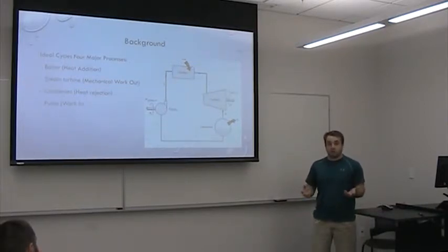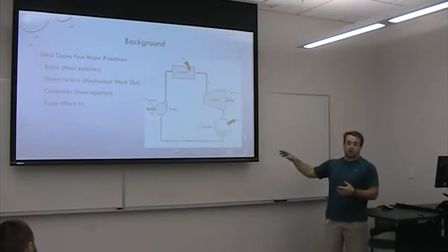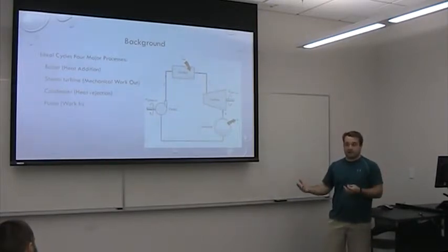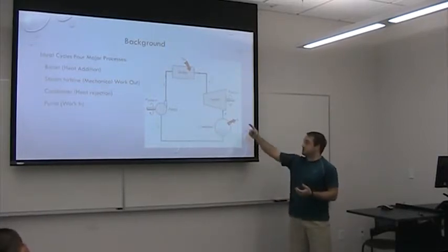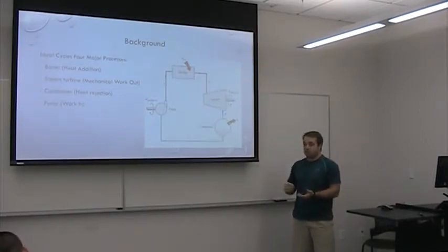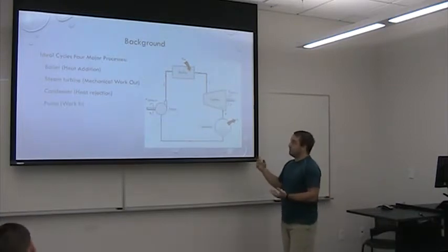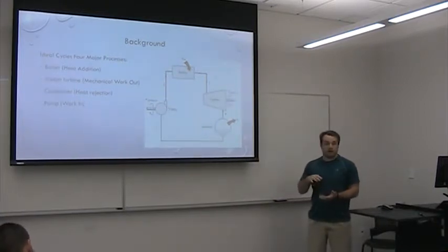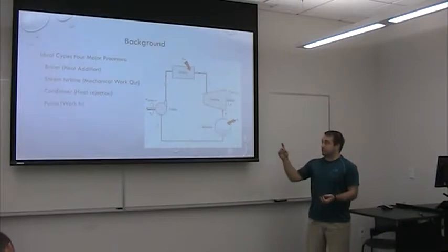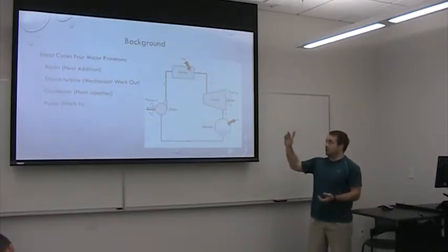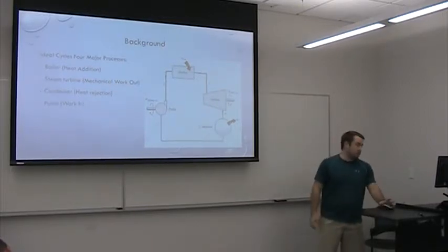This is a closed loop cycle. And this is all the theoretical version, the ideal Rankine cycle. In a real system, you are going to expect losses in the condenser, the turbine, the boiler, and the piping because of friction. Through the boiler, you're also going to have heat losses, which will have different effects. Because of the pressure losses from friction, you're going to need more power pumped in to make up for that. And for all the heat losses, you're going to have more heat added in the boiling process.